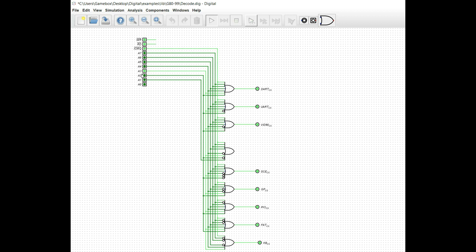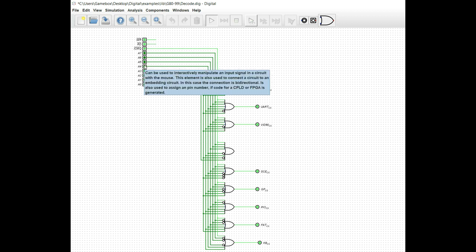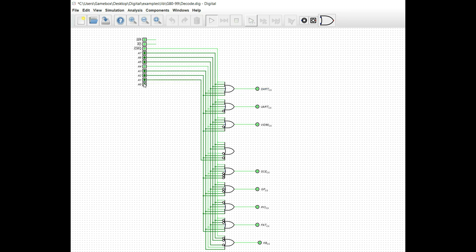Let's just go through these one at a time. The next one is going to be 10. So we see that on the Video 80 chip select we're getting an out. I don't have the rest of the logic hooked up for the VDP, the TMS video controller that is, so we're going to skip that one for now.